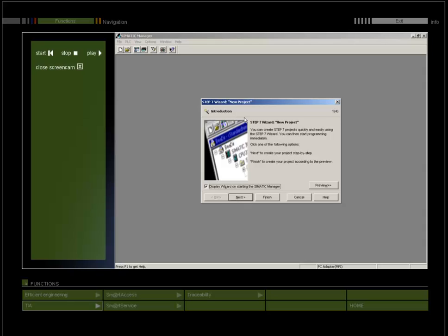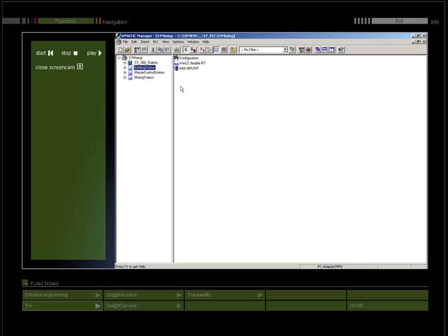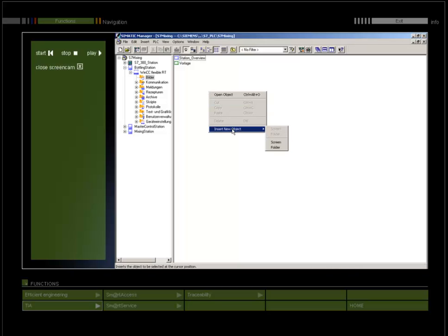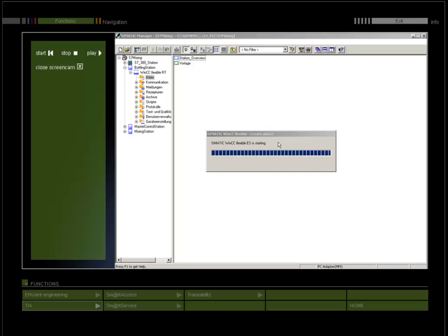If you are using a SIMATIC controller and have installed the Step 7 configuration software on your system, you can integrate WinCC Flexible in Step 7. The SIMATIC Manager serves as central control point for the creation, processing and management of the SIMATIC controllers and HMI operator panels. You have access to all objects in WinCC Flexible via the SIMATIC Manager.